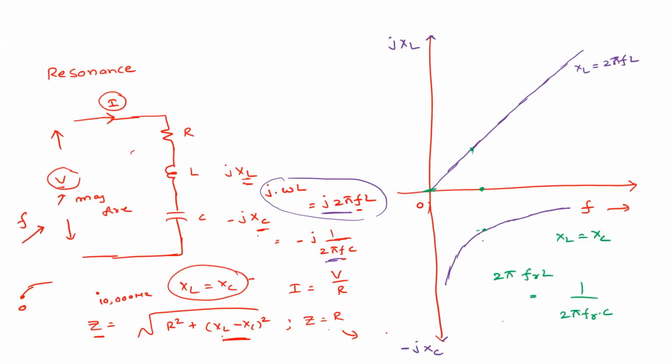This curve is varying like this, agree? And this is varying like this, right? Understood? Yes, sir. So at a certain point, this is maybe XL, some value, and this is also some value, XC. If you change the frequency, at a certain point this XL may be equal to XC, right? Yes, sir.